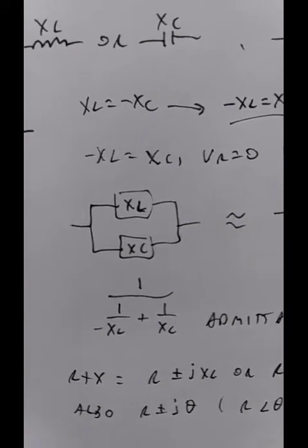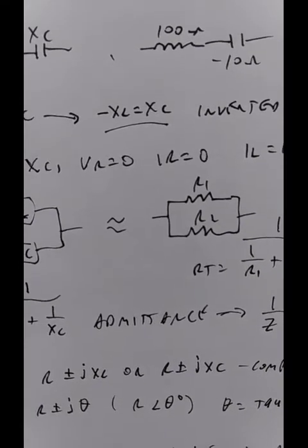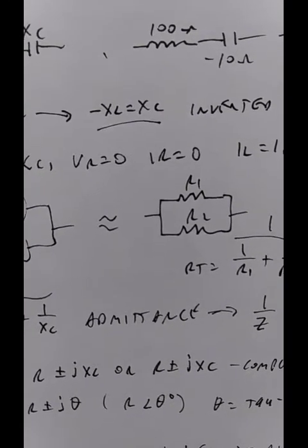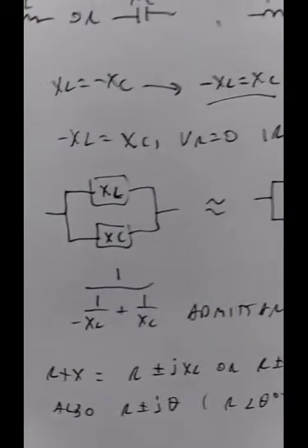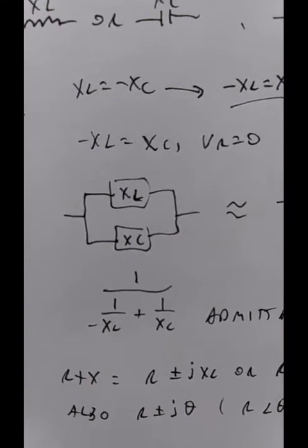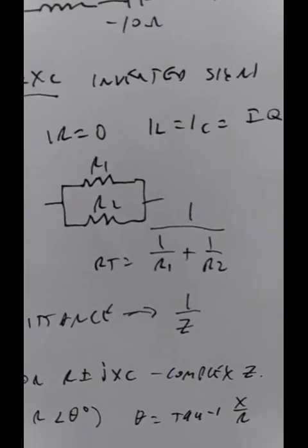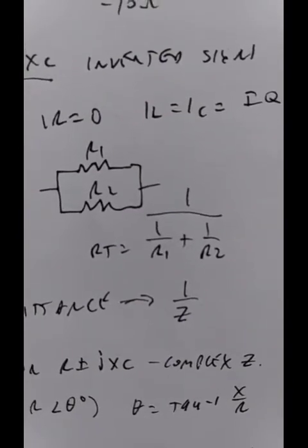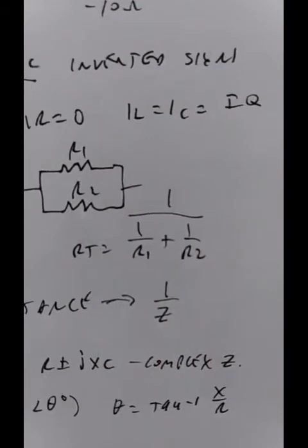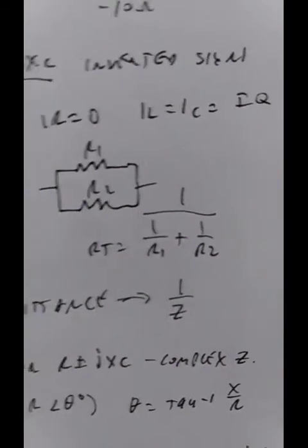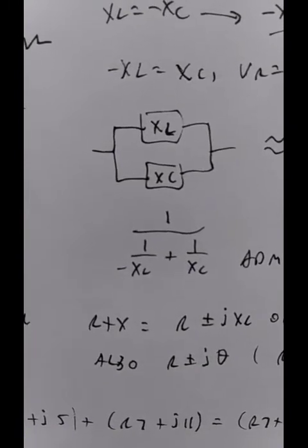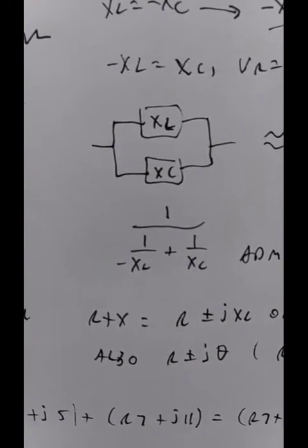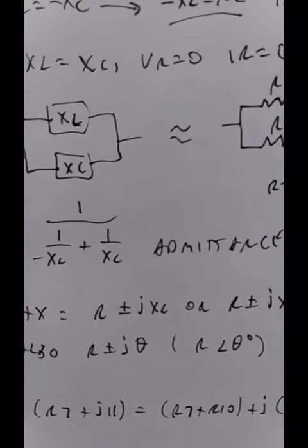There's the X sub L and X sub C in parallel. That's approximated by two parallel resistors. That's two parallel impedances, pure impedances, no resistance. They combine by a similar law as two parallel resistors. Invert each value, add them, invert them again. Same with reactances. Invert their values, add, invert again, although it cannot be done with simple algebra.